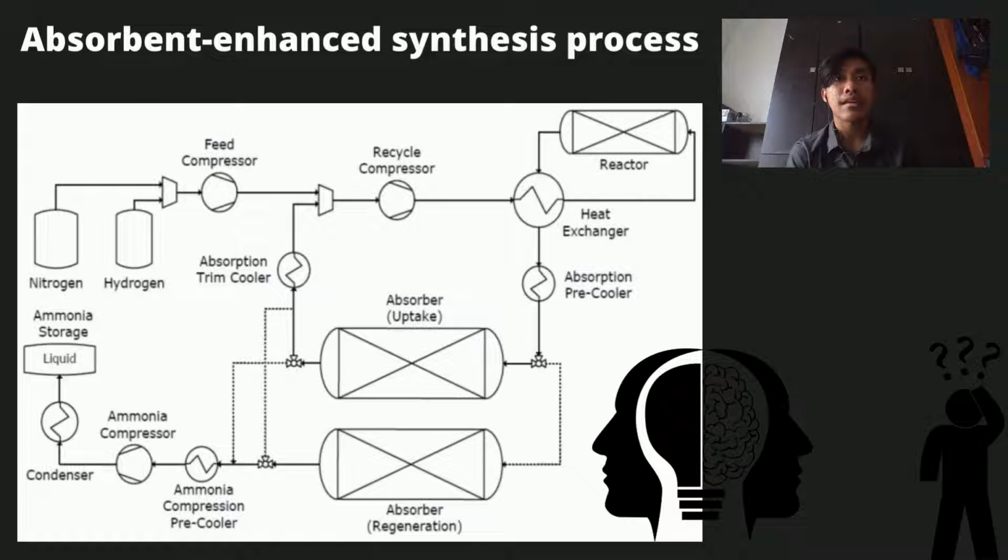At the end of the absorption cycle, once the absorber is deemed saturated, it is regenerated through a combination of heating to between 400 and 500 degrees Celsius and decreasing the pressure by opening one end of the vessel. This causes a reduction in the ammonia storage capacity of the absorbent, and subsequently ammonia is released to the gas phase. This gas leaves the bed through the open end due to the pressure gradient.